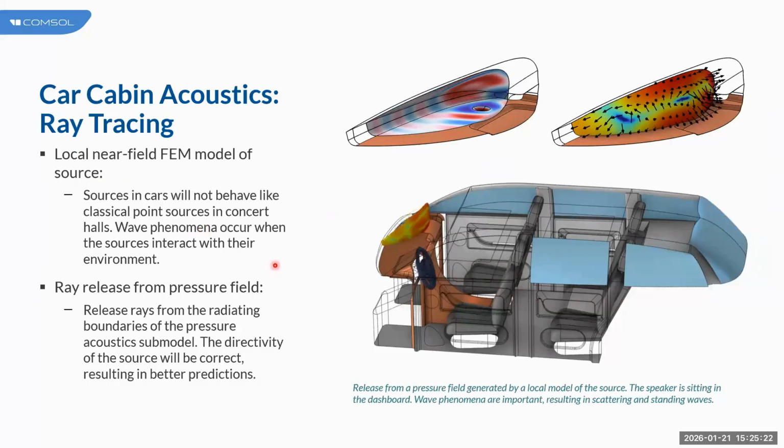So yeah, when we work at very high frequencies, the meshing requirements are high because we need to resolve the waves when we deal with medium to very large scale geometries. And here is where we usually switch to a ray tracing approach.